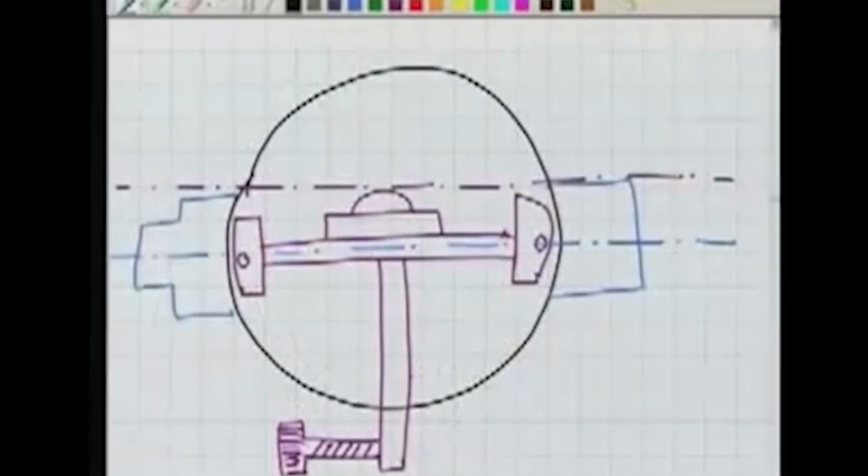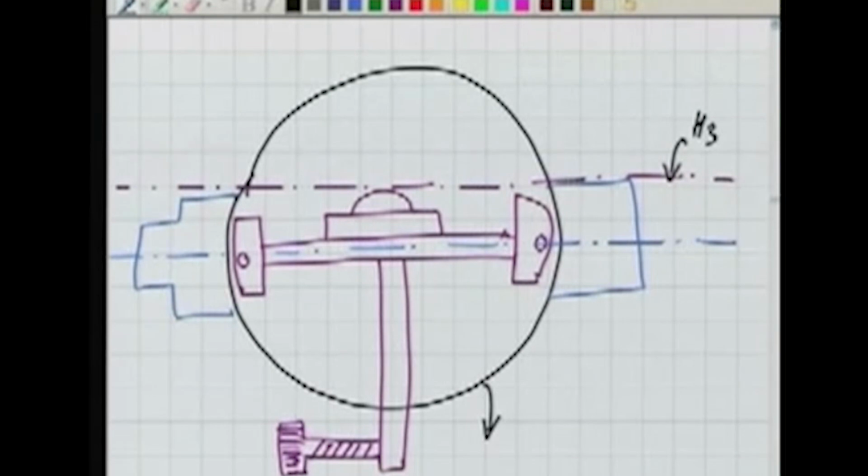Well, this is the case. This is the vertical circle here, and this frame is the frame of the altitude bubble. The altitude bubble is in center, so this line is horizontal. In ideal case, this blue line, when the reading is 0 and 0, should also be horizontal. Now let us say this is not the case. The line of sight is now inclined because of some problem with the instrument. We'll come to that particular problem, where the problem lies, and we will see the effect of this also.